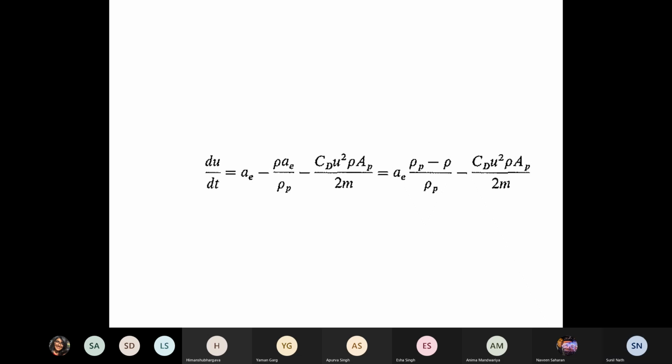Now, projected area is also a general concept. I can project any irregular shape onto a plane perpendicular to the motion. Why not? M I can measure, rho I know, rho P I know, AP I can obtain by the projection, delta rho I know, G is G. But you can also obtain another expression like this, which I haven't put down here, by replacing the G by R omega squared.